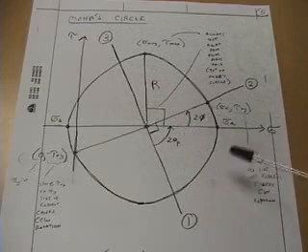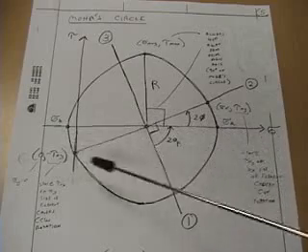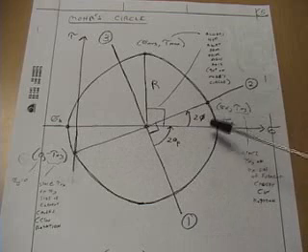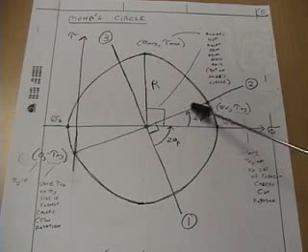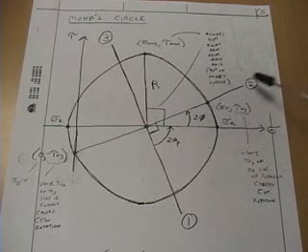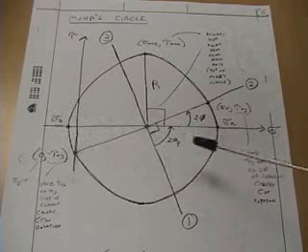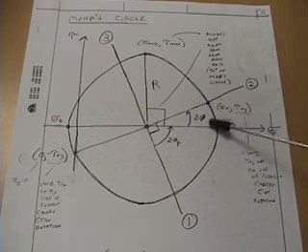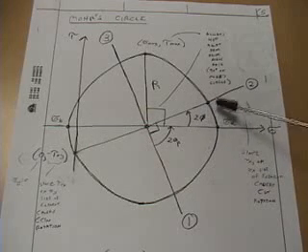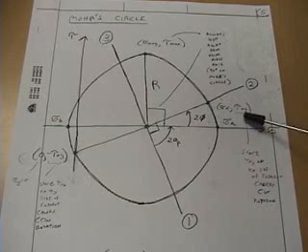The strain gauge rosette equations allow us to calculate sigma A and sigma B, the maximum and minimum principal stresses, and we calculate that angle phi that tells us where the principal stress is located relative to gauge 2, which is aligned with the axis of the tube. Since we know the principal stresses from the rosette equations and the direction to the maximum principal stress, we can use that information to calculate the stresses in the direction of the element, so sigma x, tau xy.